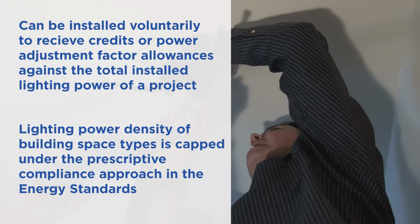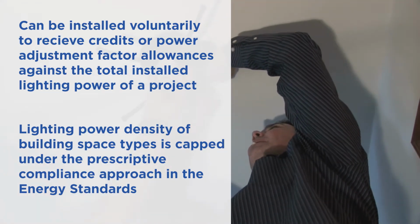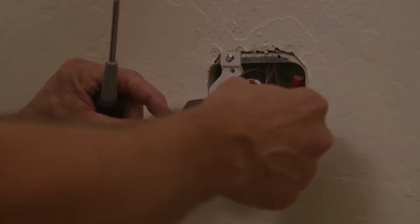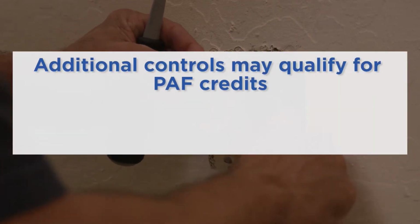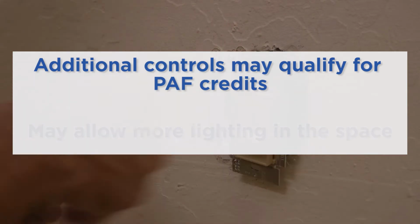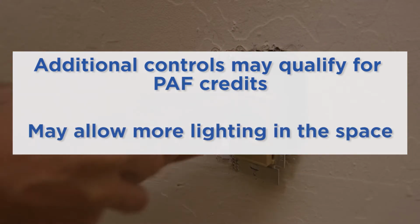Lighting power density of building space types is capped under the prescriptive compliance approach in the energy standards. Installation of additional lighting controls will further reduce the overall energy consumption of the lighting system, so credit is given for these measures, allowing building owners and designers to add some additional lighting in the space if needed.